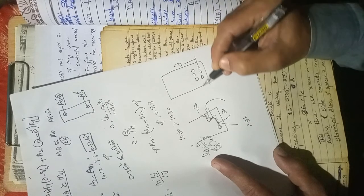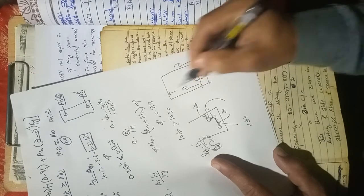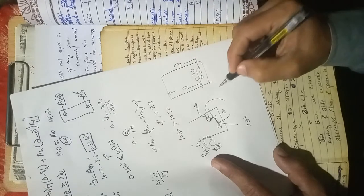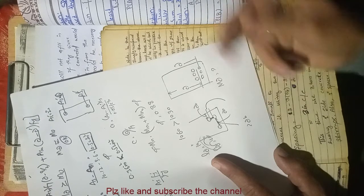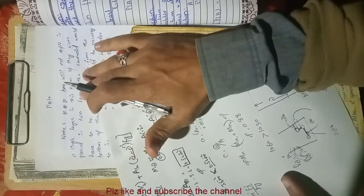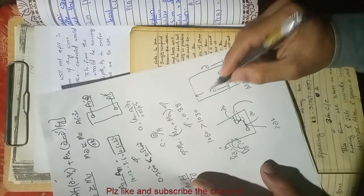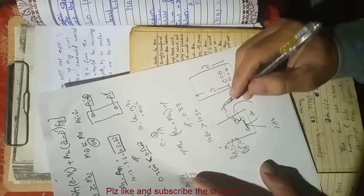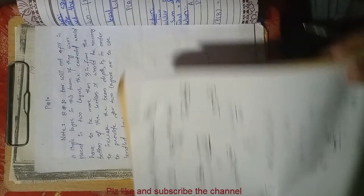Now if you place the bars in a double layer, your d value will be decreased. If your d value is decreased from the previous one, it will affect your moment capacity. So let's say you detail this beam, the example we did here, find out the d value, and then recalculate the moment capacity. Your moment capacity will again decrease. So this is again a problem for us.